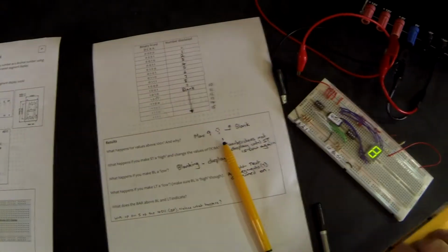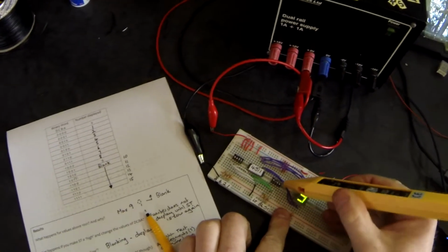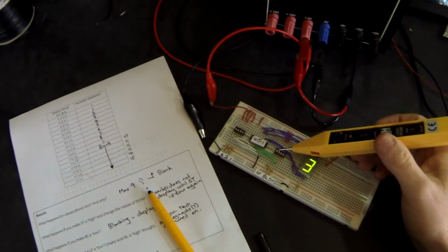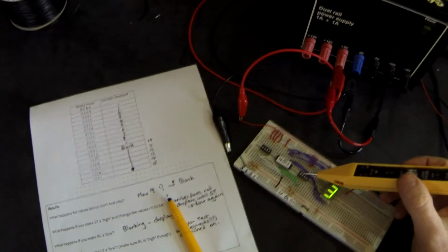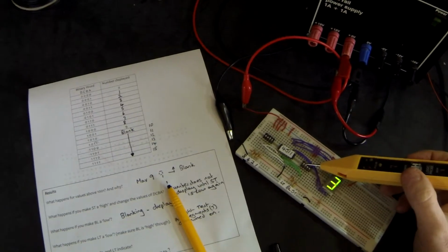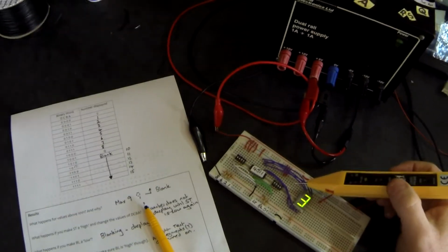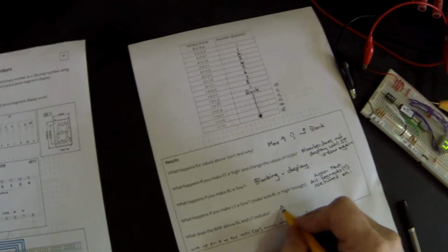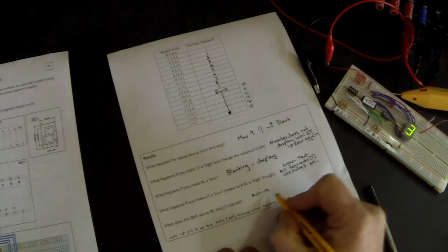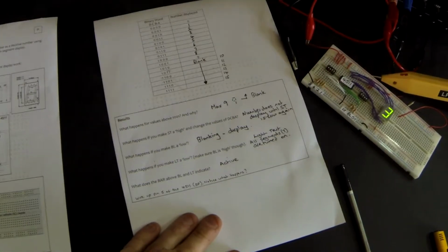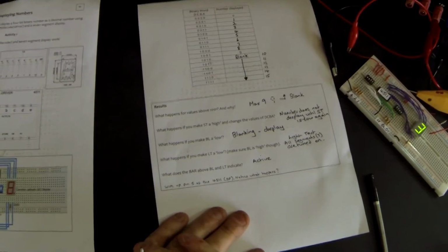So in other words, we normally hold both LT and BL high. Here they are high. And when we make either one of them low, they do their job. In other words, they are active, they are turned on. So the bar indicates it is active. In this case, active blanking or active LT, lamp test, or light test as it's also known.